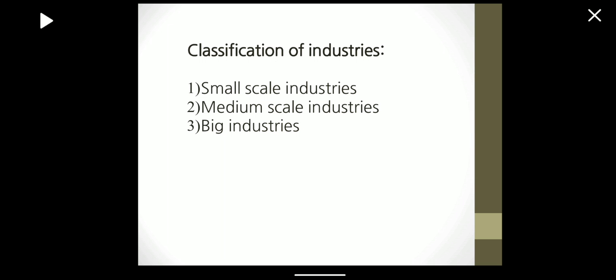Then next is big industry. This industry produces machines, articles, and mobile vehicles on a large scale. Machine activities are continuous in 3 shifts. Power requirements are on a large scale. A separate high tension 11 kV line from the supply company is in the premises of the industry. Bill payment to the electricity company is as per a separate tariff. That means sometimes maximum demand tariffs are required for these big industries.